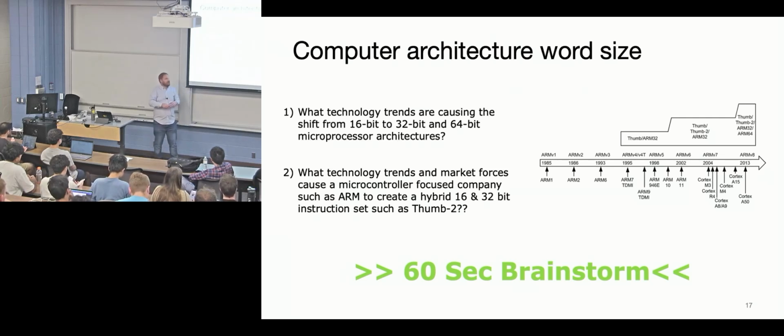So to that size, keeping the 16-bit around lets you have smaller size and be more flexible, even though they could go up to 64-bit architecture, just not going to gain that much from making that big transition. So instead, ARM in general focuses on the lower, more power efficient, give up performance, but let Dennard scaling and Moore's law make those transistors more efficient. And then they'll build a hybrid ISA just to get the most they can out of that little lower end piece of silicon.